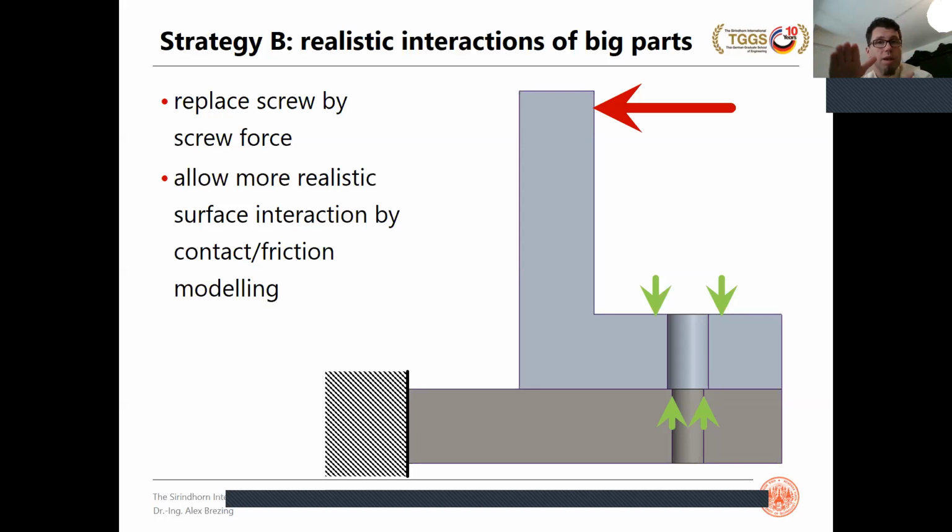So this time we will not completely bond the two surfaces, the contact surfaces, but instead Chinnawit will choose an appropriate surface contact condition that actually allows for the surfaces to lift off from each other but not go into each other. And there's even the effect of friction between those. And this is necessary because if the two surfaces could move without friction, then the external force would just push the L away. So this is actually some pretty high level simulation that we'll do right here.